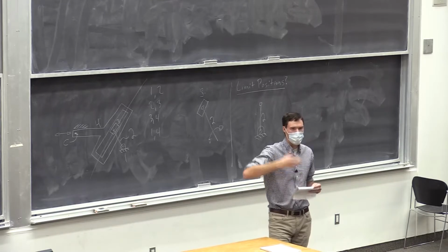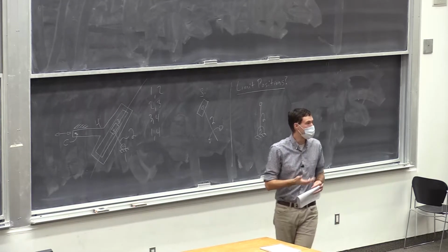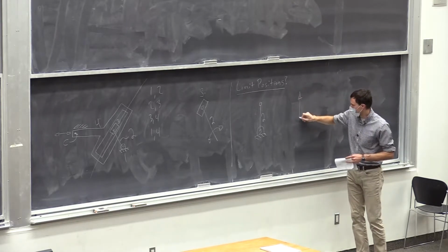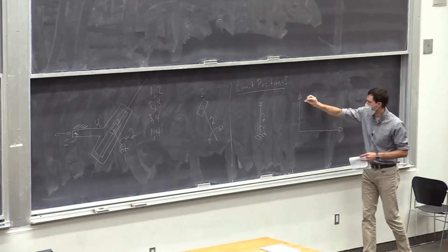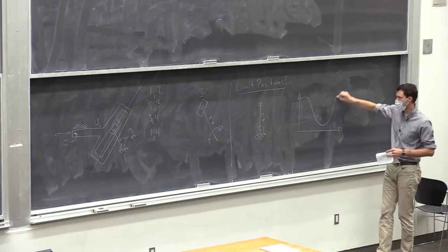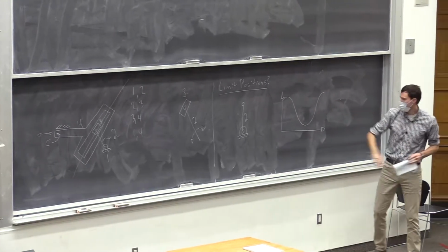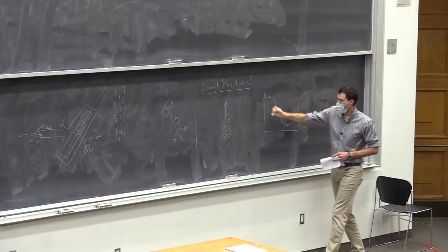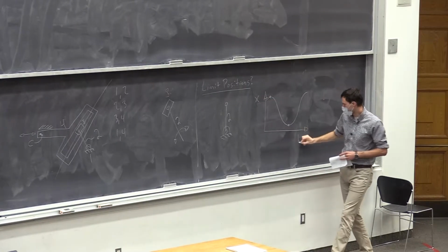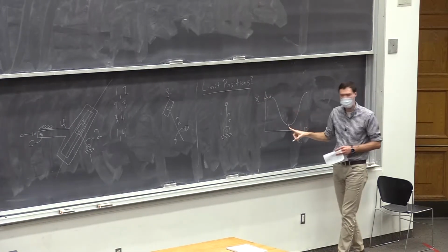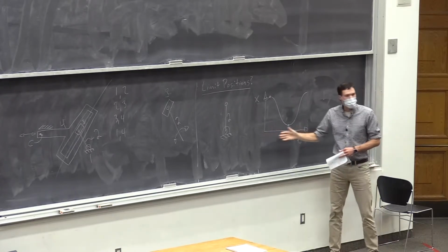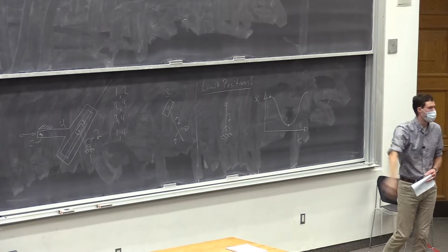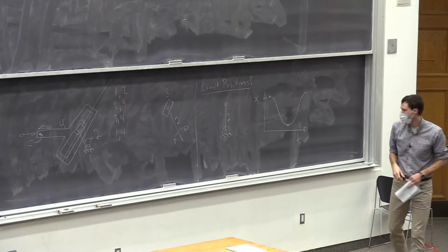The reason that I mentioned constant is because when we're doing timing ratio, remember in lecture I drew out this nice plot for the slider crank mechanism. Different mechanism, but we plotted this out, and we found these limit positions were like the max x position over time, maximum x position. But we assumed that the input was going constant, right? And so in that mechanism, the input could go round and round continuously.